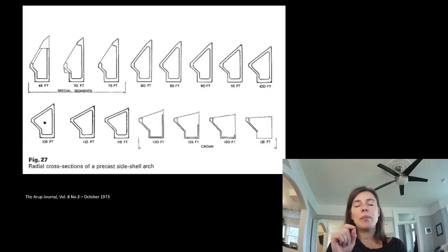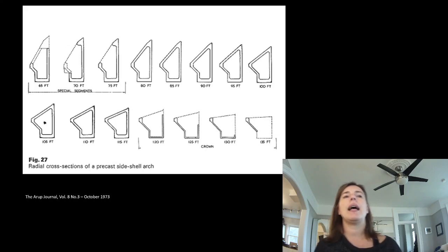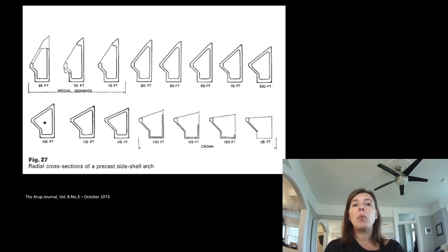I like this one because this one's really handy for structural drawings. And we do this a lot when we need to show structural information. What's happening here is this is all one member cut at 5-foot segments along its length.